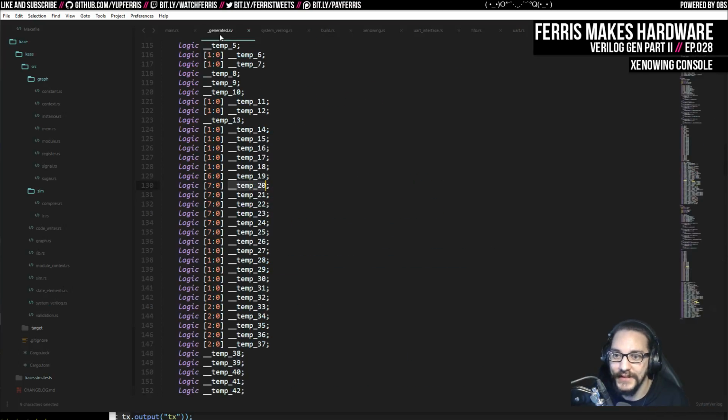So what ended up happening was that this was generated with a bit width of 1. So it looked like this instead. And Verilog has no issues with that, which is one of the reasons why I have a hard time writing Verilog a lot. One of the things I really don't like. I like these kind of casts to be explicit. And in this case, it happily accepted that.